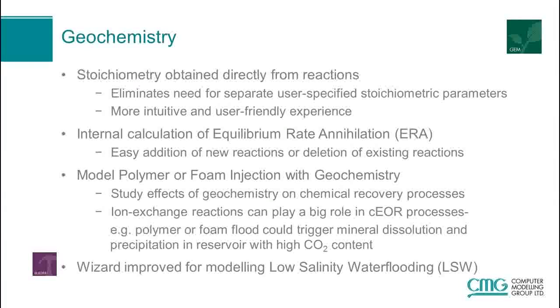We also can model polymers and foam injection with geochemistry in GEM, which is really neat. And this helps us study the effects of geochemistry on some of these chemical recovery processes, particularly how ion exchange can play a possibly pretty large role in some of these. A good example of that is, of course, when you inject a polymer or a foam, and you could trigger a mineral dissolution or precipitation in the reservoir if you have a high CO2 content. It's almost quite similar to doing a CO2 EOR or CO2 sequestration in some cases, depending on how the water chemistry and rock chemistry interact.